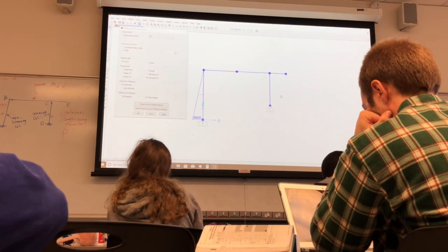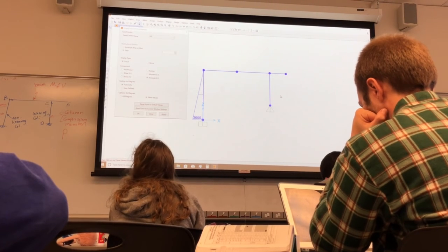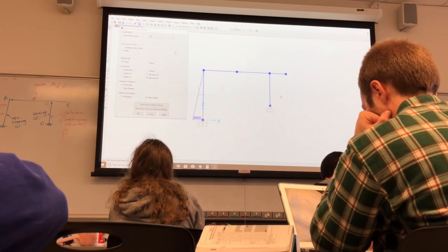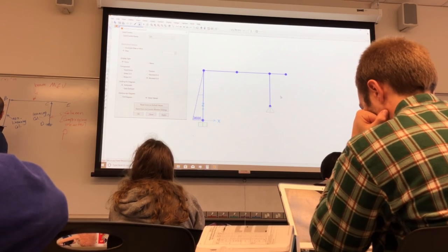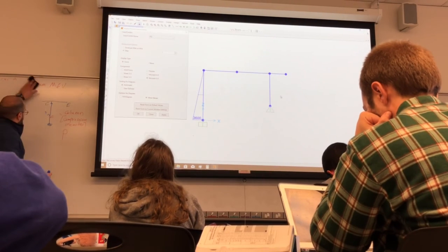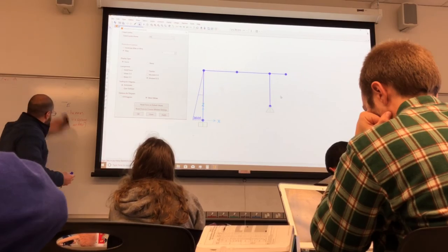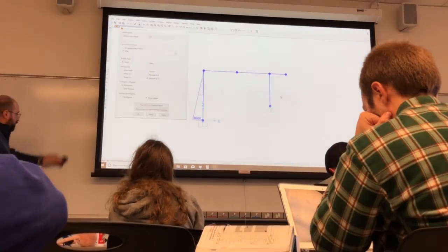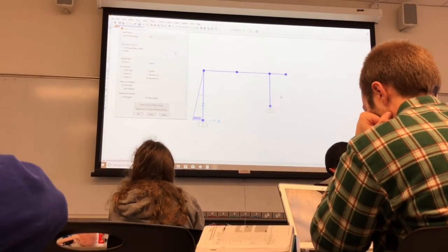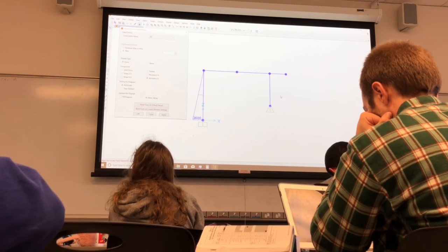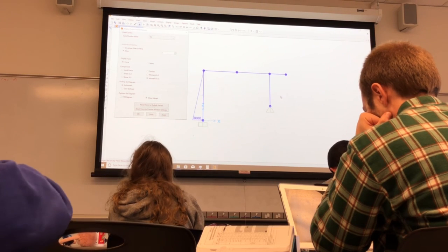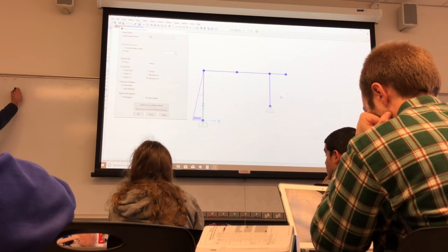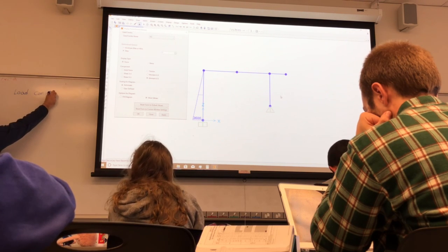These are not what I'm going to use for design. I'm going to do the load combinations for design. We usually do that in Excel, but let me do it by hand once and then we use Excel. Next class we'll be using Excel to do the rest, because it's a lot of calculations. So we create another table called the load combinations, or load combos.